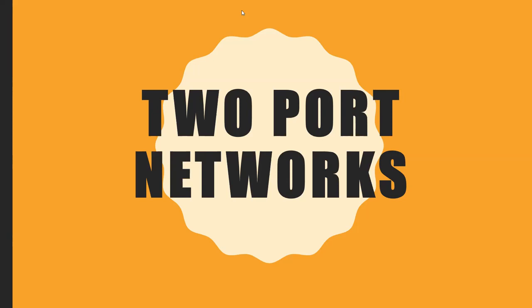Yes, sir. So you'd have two voltage sources there, which would have given you the line-to-line voltage. And if you think of those as voltage sources, then you just go ahead and write two mesh equations. I didn't think of that, sir. That's all right.